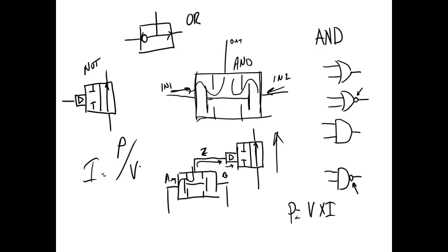If they give it to you in inches, that means that is the bore diameter, and you've got to find the area. Now for the rod side, you've got to take the bore area minus the rod area. Right? Unfortunately, that worksheet doesn't have any of that on it. But it was on that other worksheet where they gave you the area. That makes sense?